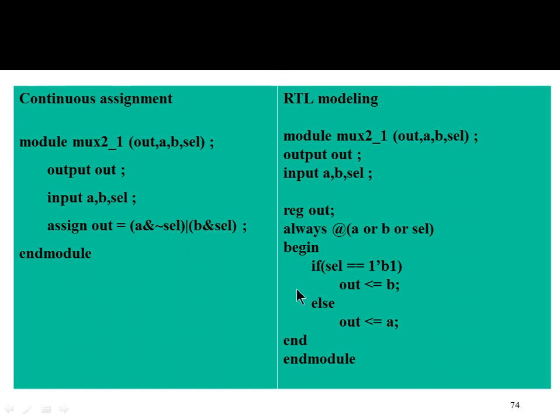The assignment rule for a register, in case I'm going to assign directly to the output, is that if I'm going to assign a value to output inside the always block, then I need to have a register with the same name. Only then, since it's the same name, internally they will be connected. So if I assign some value to a register inside the always block, that goes to the output as well. But that's the assignment rule: I have to have a register with the same name.